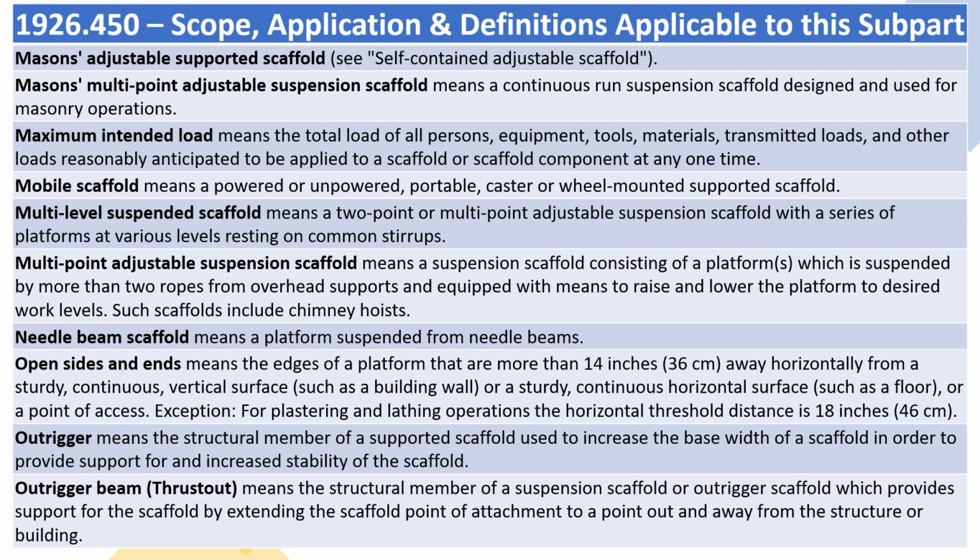Mason's multi-point adjustable suspension scaffold means a continuous run suspension scaffold designed and used for masonry operations. Maximum intended load means the total load of all persons, equipment, tools, materials, transmitted loads, and other loads reasonably anticipated to be applied to a scaffold or scaffold component at any one time. Mobile scaffold means a powered or unpowered, portable, caster or wheel-mounted supported scaffold.